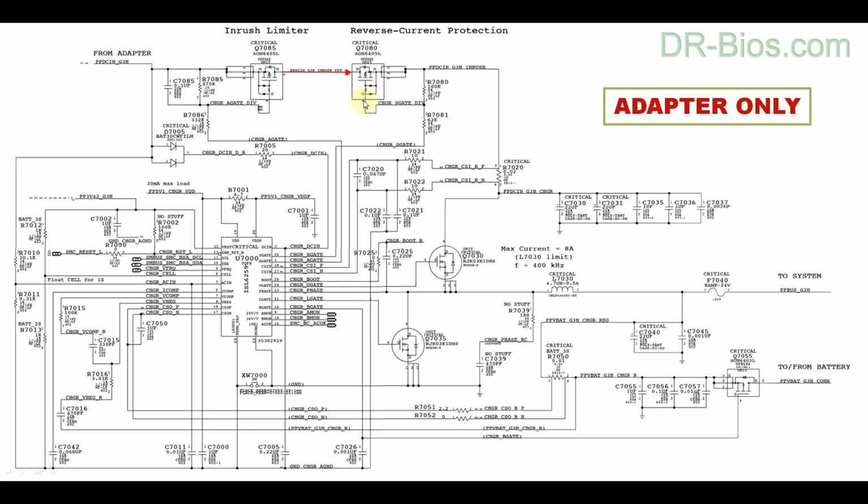And as you see, this P-channel MOSFET has aligned diode body with input voltage, and that prevents reverse current, meaning battery voltage won't enter adapter, so that by plugging the adapter out of outlet while the jack is still plugged into the device, battery voltage won't enter the adapter.